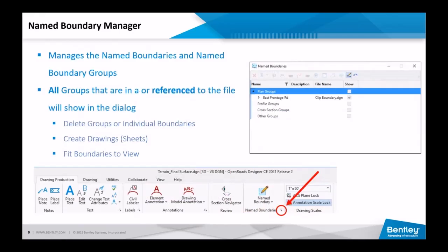All right, where can you manage your name boundaries? And that's your clip boundaries that you created for your sheets, and that is in the Name Boundaries Manager. And so that can be accessed from this little launcher on the ribbon. There's also a key-in.